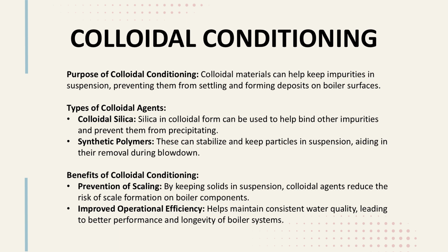Two commonly used agents are colloidal silica and synthetic polymers. These substances act as stabilizers, preventing impurities from forming solid deposits. The benefits of colloidal conditioning include improved operational efficiency and the prevention of scaling, both of which contribute to a longer boiler lifespan and more consistent performance.